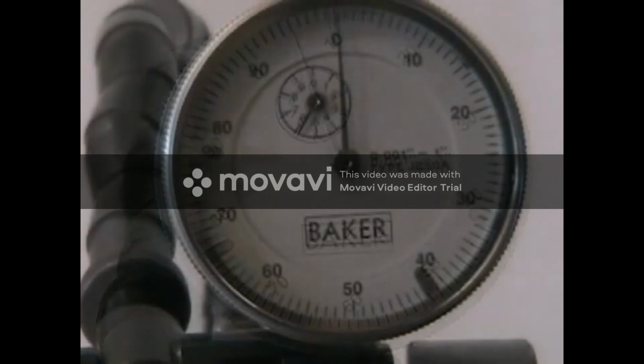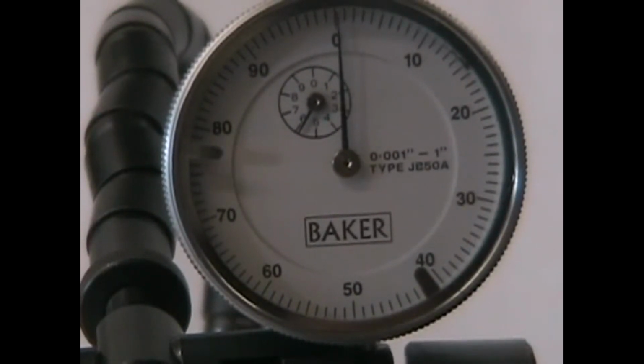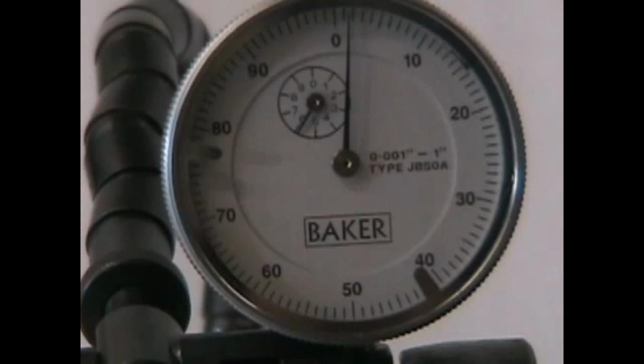In this example, the needle starts at 0 and moves between the 1/1000ths and 2/1000ths inch lines. Since each line is 1/1000th of an inch, if the needle is between them, it can be either rounded up or counted as 5/10,000ths of an inch. The total runout for this part is 15/10,000ths of an inch.